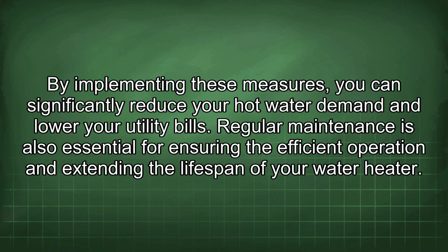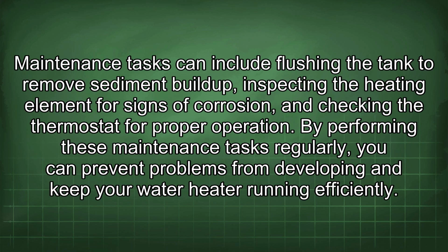Regular maintenance is also essential for ensuring the efficient operation and extending the lifespan of your water heater. Maintenance tasks can include flushing the tank to remove sediment buildup, inspecting the heating element for signs of corrosion, and checking the thermostat for proper operation. By performing these maintenance tasks regularly, you can prevent problems from developing and keep your water heater running efficiently.